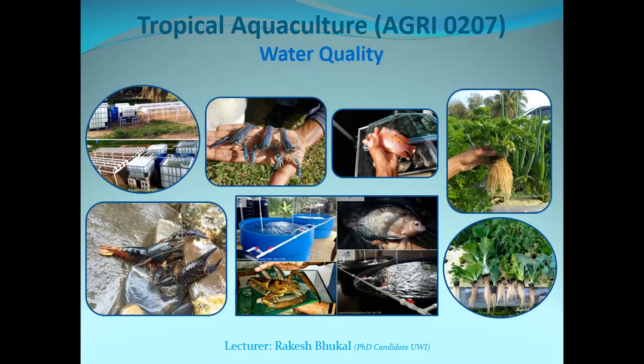Look at all the different components we covered when we did tank culture. We had the fish tanks, mechanical filtration, biological filtration to convert ammonia to nitrites to nitrates, and aeration with the air pumps, etc. The purpose of all of these is really to maintain your water quality and keep the parameters within the optimum ranges for the particular organism that you're culturing.